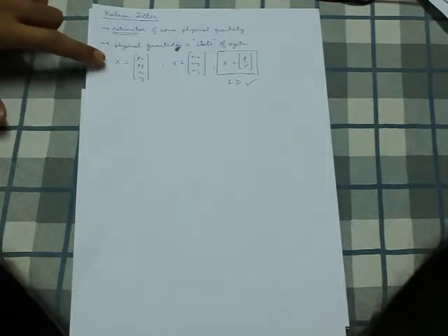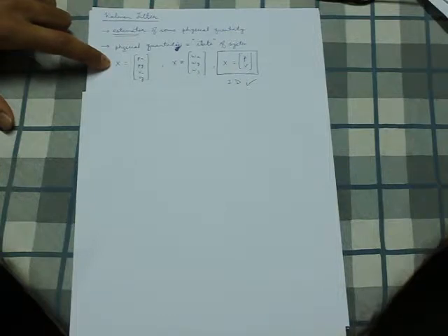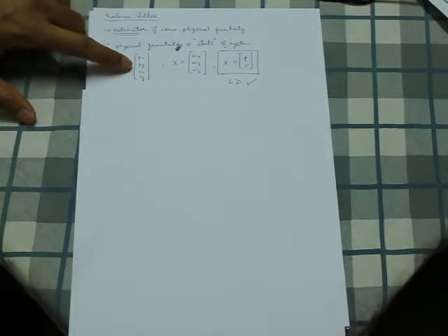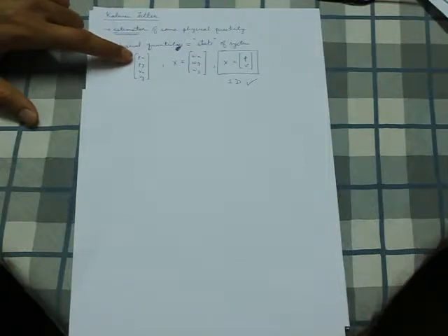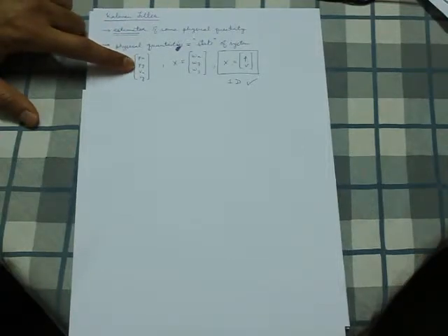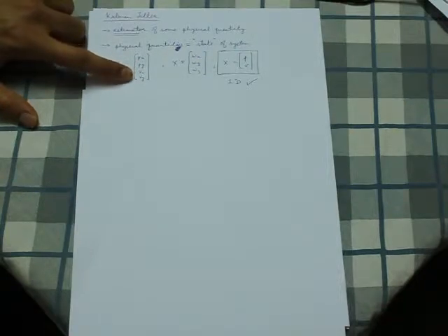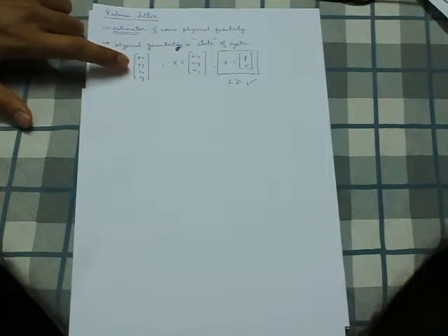So we use the mathematical model along with, say, the IMU or the gyroscope or various other sensors from the robotic arm to estimate that angle. So in control systems in general, a lot of the times we club all of these physical quantities that we're trying to keep track of into a single variable. So in this case, that single variable x holds all the parameters that we're trying to keep track of. So in this case, it might be the position along the x-axis, the position along the y-axis, the velocity in the x-axis, the velocity in the y-axis. That may be the case for some system.